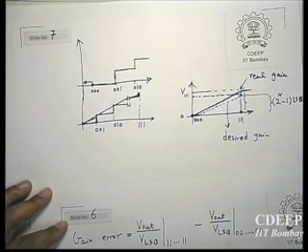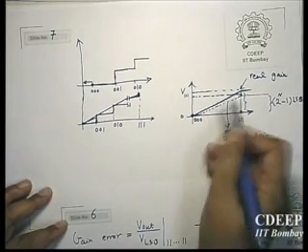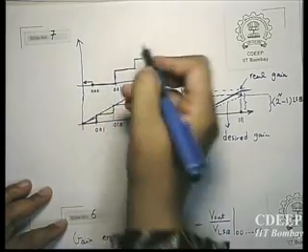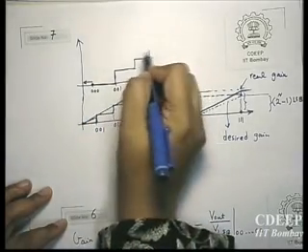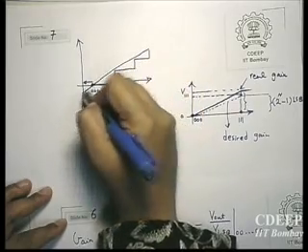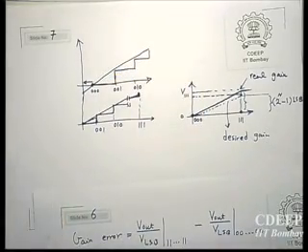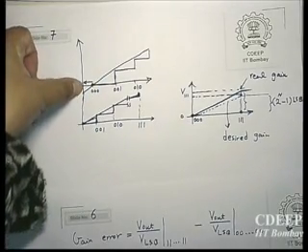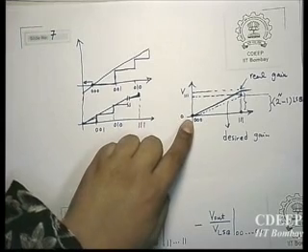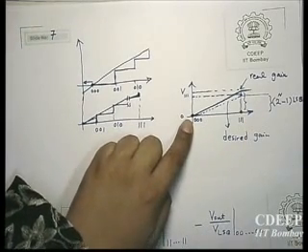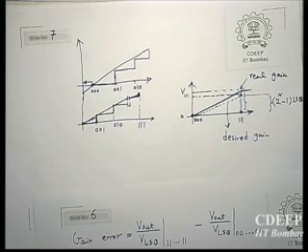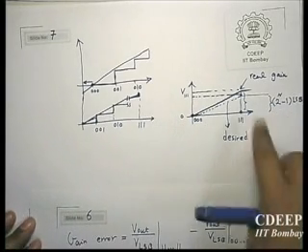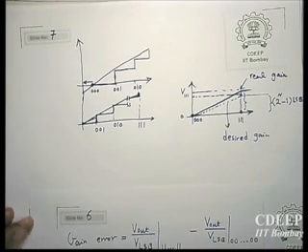And this already we have compensated. Therefore, when you plot this line, you will reach 0. If it was not compensated, you had something like this. Then when you would have connected, you would get a line like this. Then it was not reaching 0. So first we compensate for offset so that we will get exactly this first point on 0. Then now we will look at the slope of the line which is passing through 0. So this is supposed to be 2 to the power n minus 1 LSB, but then it is less or more according to the polarity of offset.